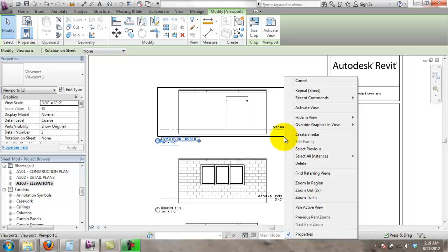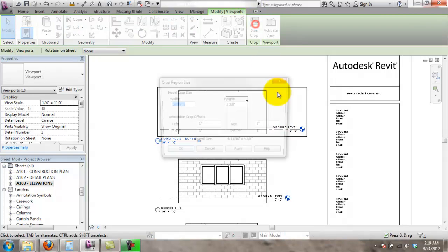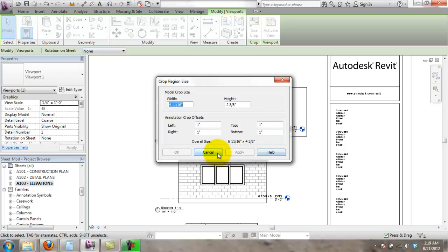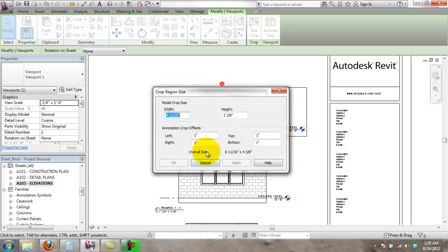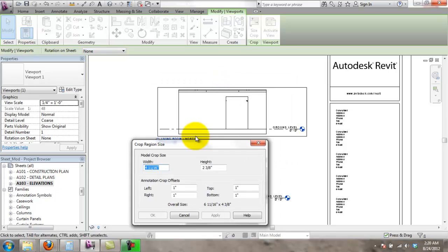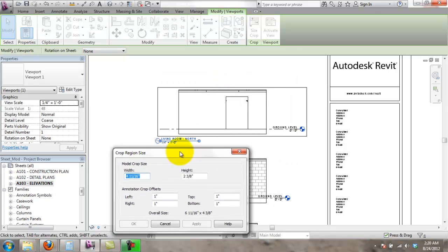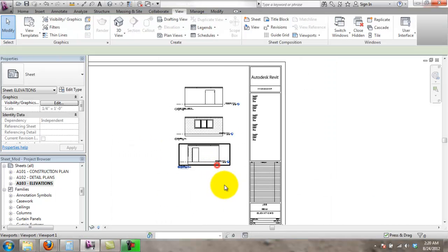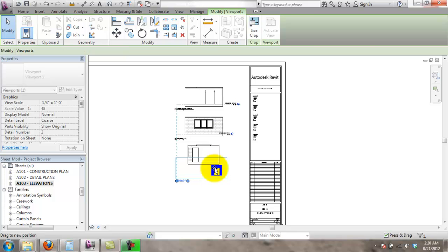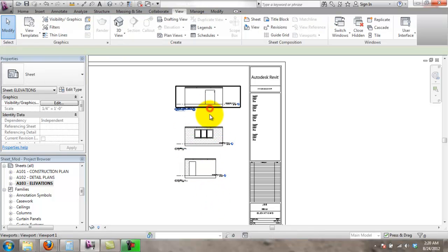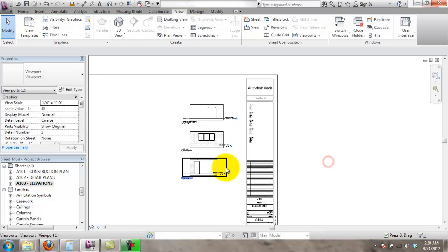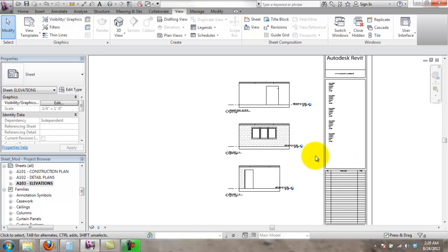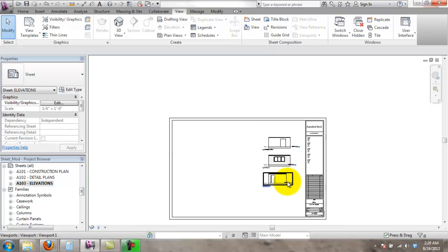Yeah, we can go all over this later. Alright, so I mean, space these however you want to. You're just using a snap to space it off of the text bubble. Just make sure you keep things to the right. You would have a lot more elevations than this, obviously, to fill up the sheet. And we had one more plan, which was the finish plan.